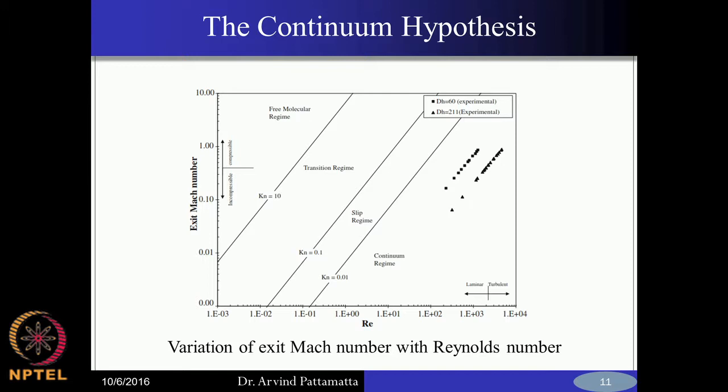So, it is a simple laminar flow regime, but you have to be careful what kind of equations you are solving. For example, if you look at the Knudsen numbers, there is no problem if you are talking about Knudsen numbers less than 0.01. In such a case, even if you are talking about a Reynolds number close to 1000, you are mostly in the incompressible regime. If you just draw a vertical line from here, and a horizontal line towards the y axis, you will find your Mach numbers are small enough to make an incompressible assumption.